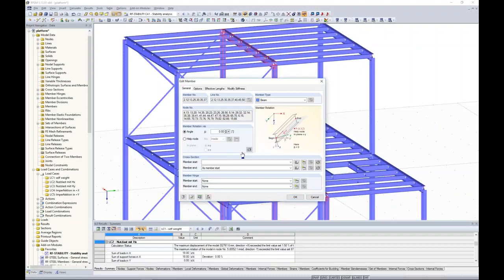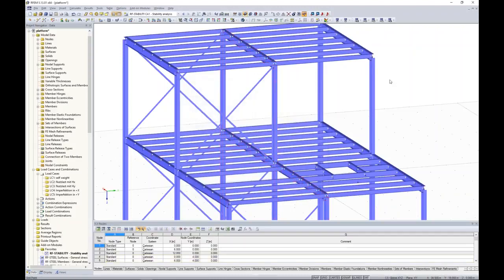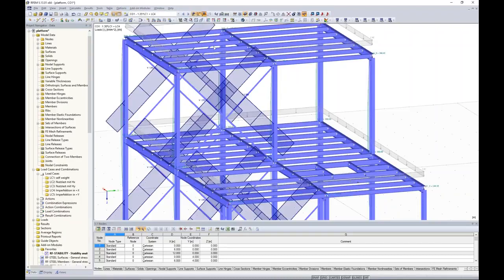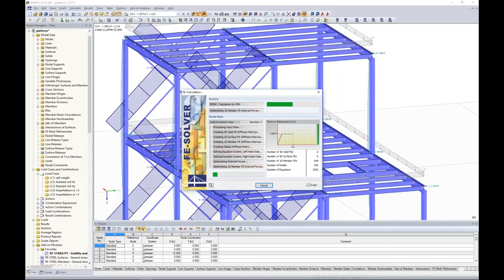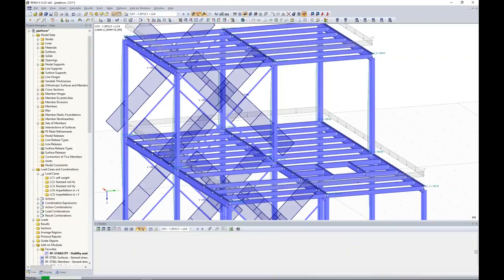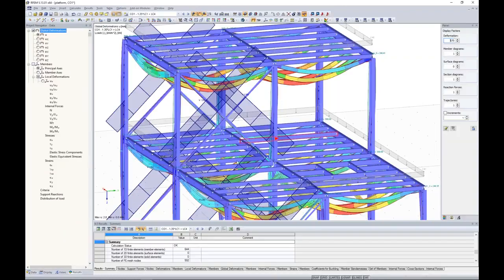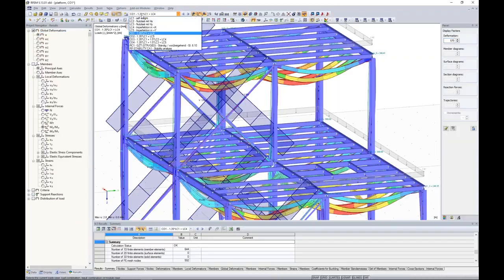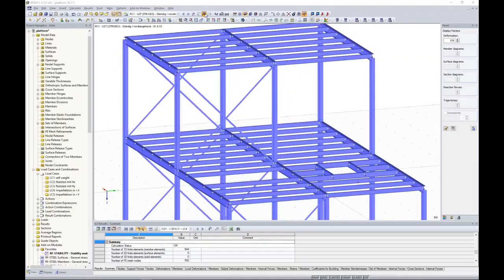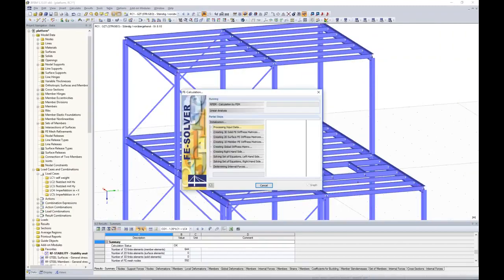Okay, delete the FE mesh, and let's try to recalculate, for example, combination number 1. And now it's like 2.8 millimeters, and it looks quite good. So let's run the result combination, and the result combination contains all of the load combinations. And if these are fine, I think the model is good. Yeah, 25 millimeters. That's the maximum. That's fine.